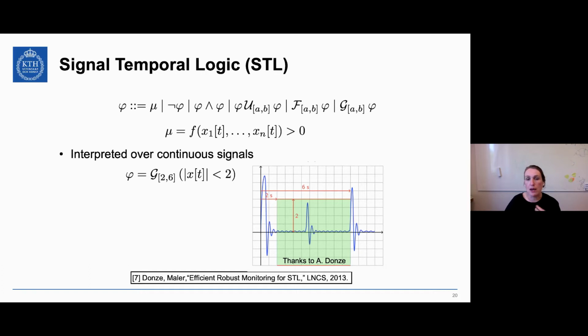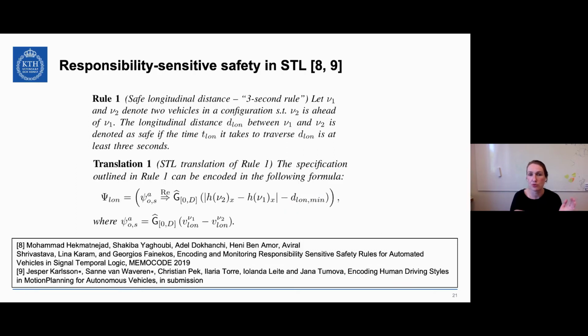But you can also ask how well it actually holds. And you can see that there is this left robustness here, 1.2 seconds, that you could have started asking for the formula to hold earlier and it would still hold. So there's robustness 1.2, left time robustness. And there is this tiny little robustness here in the values, where you see that it's actually maybe 1.9 or something. So there is 0.1 robustness. Your signal could go a little higher here. So this STL comes very naturally with a quantitative semantics called robustness of STL. And that's very nice when we will start talking about these trajectories.